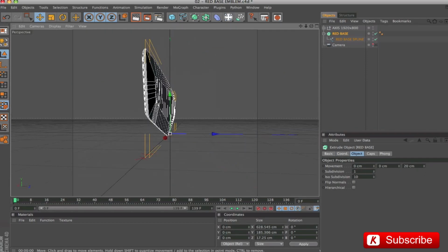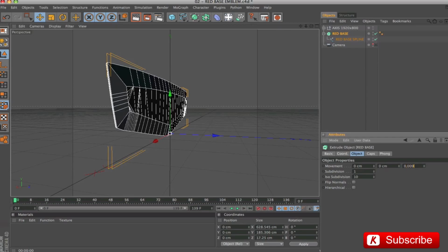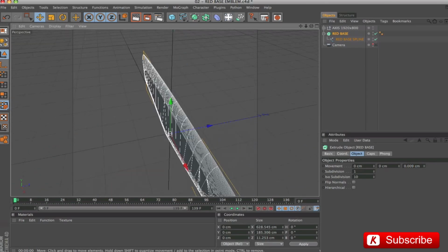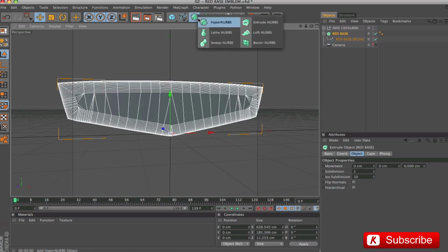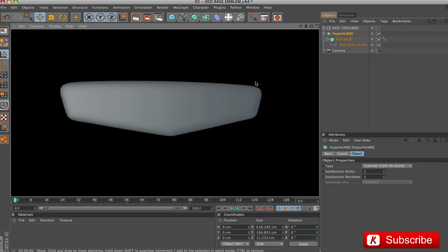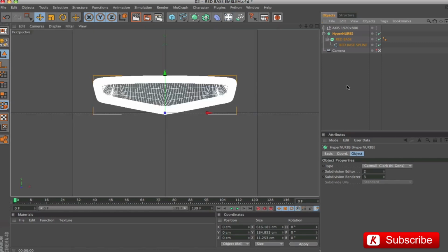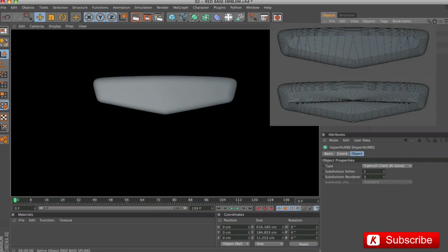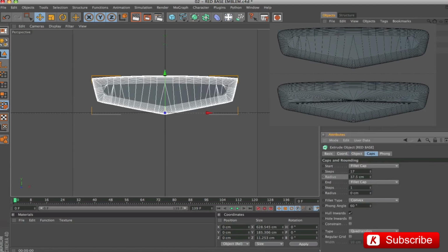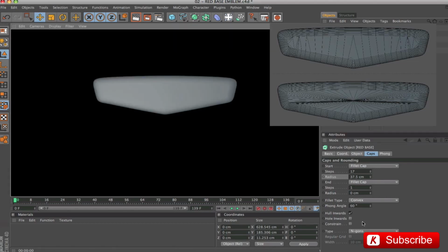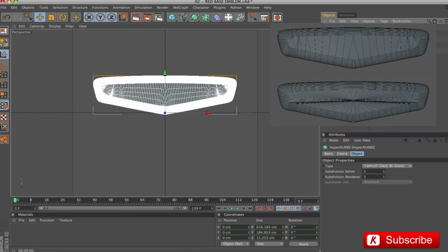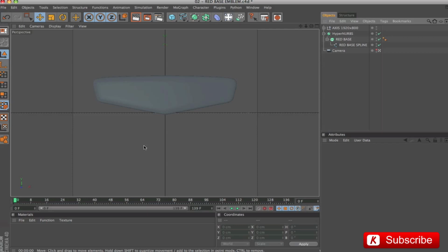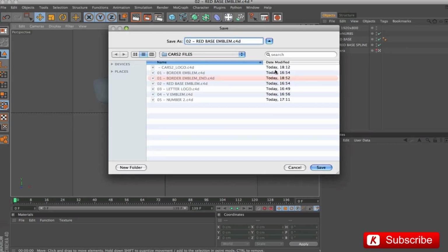We change the depth from 20 to 0.009. Insert a HyperNurbs tool. Wow! Alternatively, you can also use the N-gon mode, but it is more correct to use the quadrangles method, because if you then want to convert to a polygonal object, you have an object divided in a linear and correct way, ready to continue the modeling work on it. Save this file also with the suffix "end."